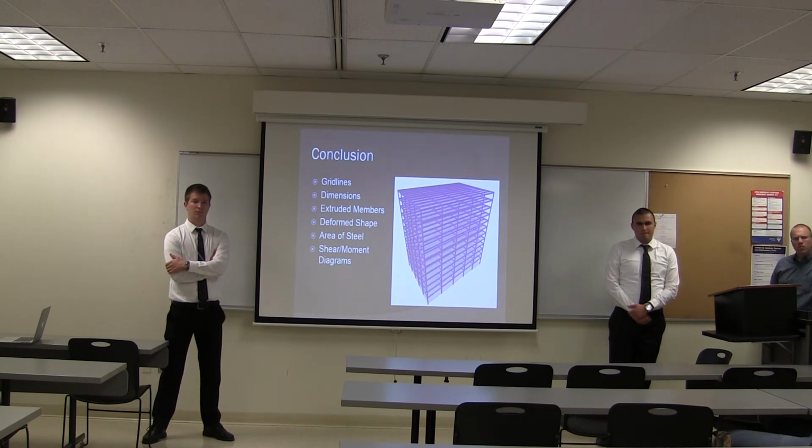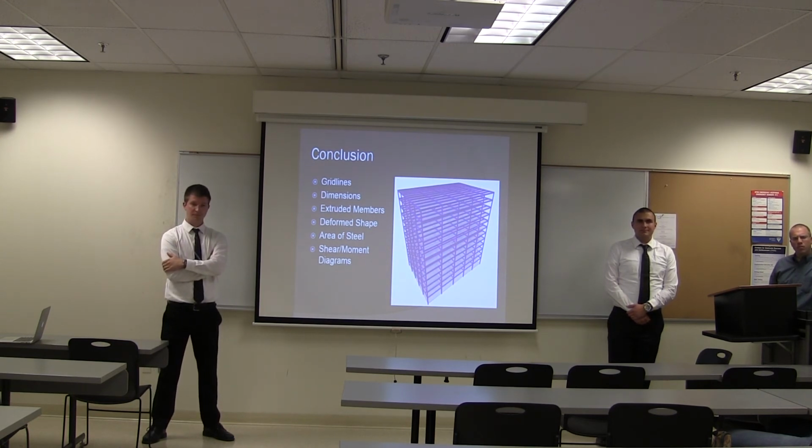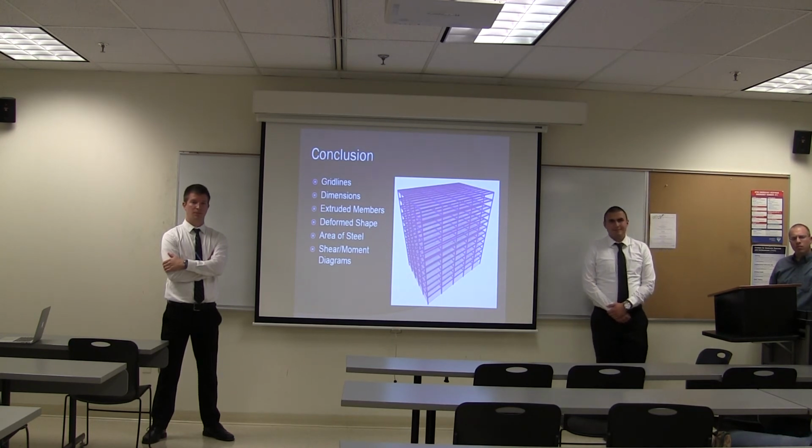The problem was not allowing me to design these beams and put shear reinforcement, so I defined them as horizontal columns pretty much. Since columns allow spacing for the spiral or the stirrups, I used that as the stirrups for the shear, and that's how I allowed the model.